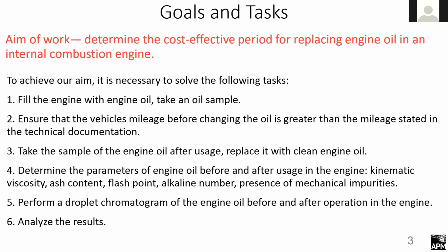The following steps were to be taken to achieve our aim. Fill the engine with engine oil, then take the oil sample. Ensure that the vehicle's mileage before changing the oil is greater than the mileage stated in the technical documentation. Take the sample of the engine oil after usage, replace it with clean engine oil. Determine the parameters of engine oil before and after usage in the engine: kinematic viscosity, ash content, flash point, alkaline number, presence of mechanical impurities.